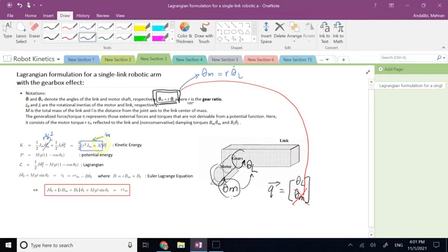So in this J equivalent, you have two terms, not really one dominant one, which is J L. If there is a dominant one, most of the time it's really the R squared J M term which is becoming dominant, unless your gear ratio is really small or you can rotate the motor at a very small RPM without the gearbox. So that's your kinetic energy.